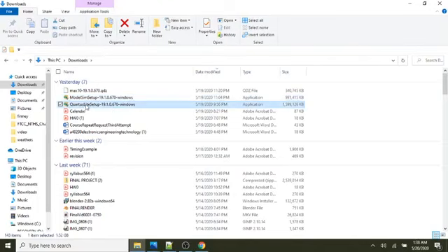Then you would just run these like you normally run an executable to install software. However, you only need to run the Quartus Lite setup, because it'll take care of the other stuff. Once you finish Quartus Lite setup, it will have already set up ModelSim, and if you had hardware, it would have set up that device.